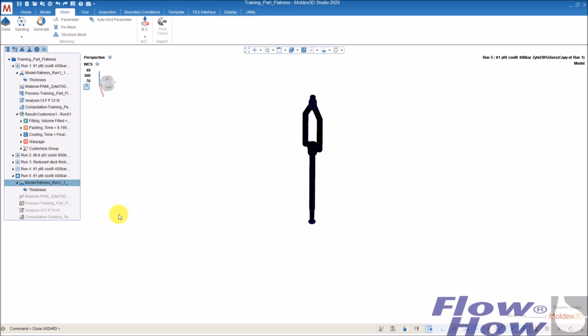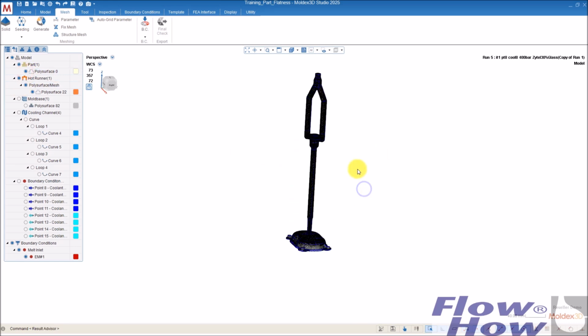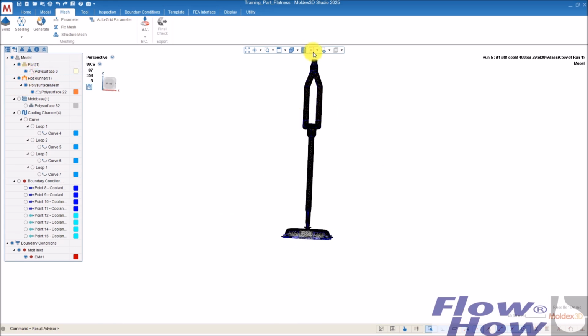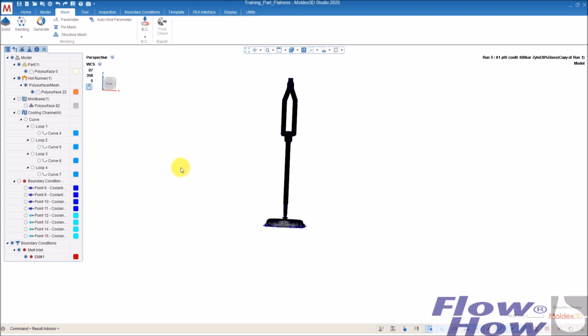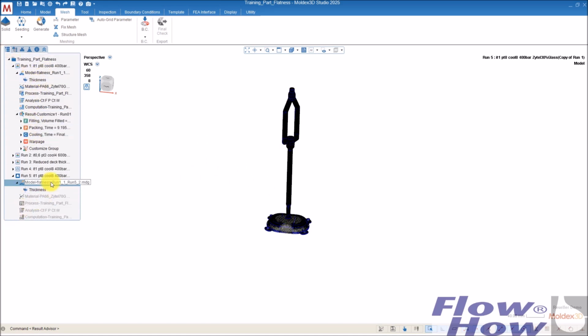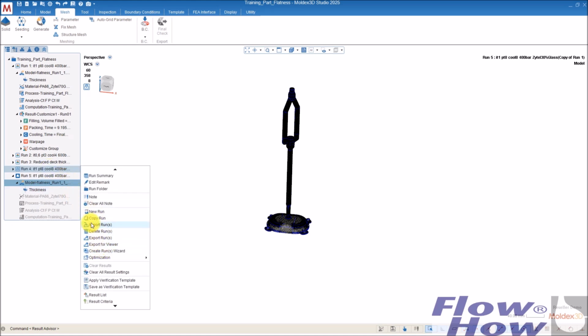The last thing I want to show is how you can combine things, because now I have the small runner, the small part, with a cold runner, just a pin gate, and then I have a big part with the hot runner. Now I want the small part with the hot runner and also the mold base that I've just changed. Of course, I could start the same procedure as I did before, but the easiest way is a bit different.